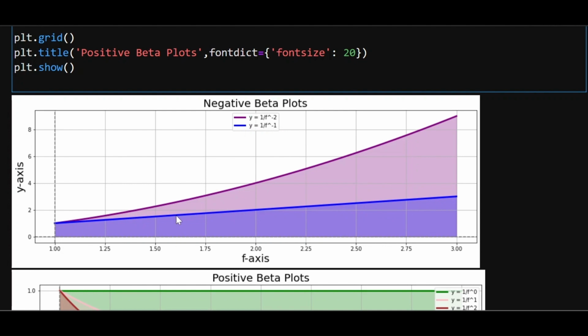And beta equal to -1 is nothing but blue noise, and that's the reason why it is shown in a blue plot and blue area under the curve. What it essentially means is that the higher frequency components of the noise will get amplified or will have higher energy.